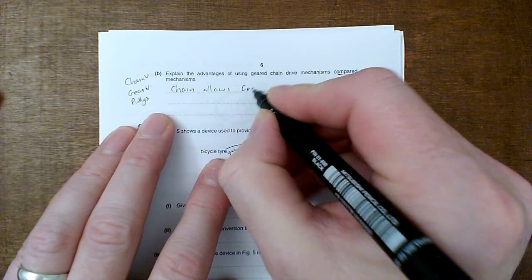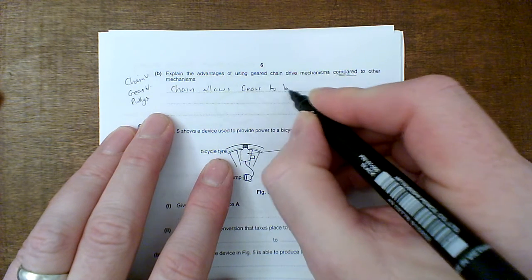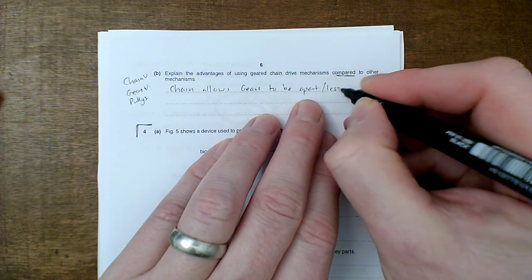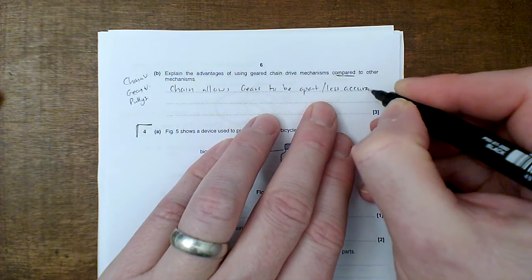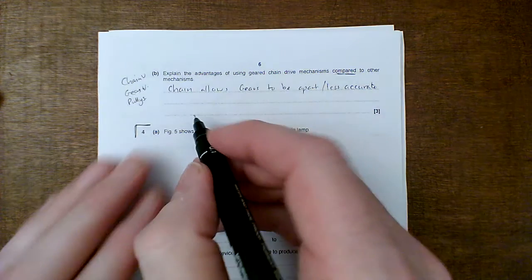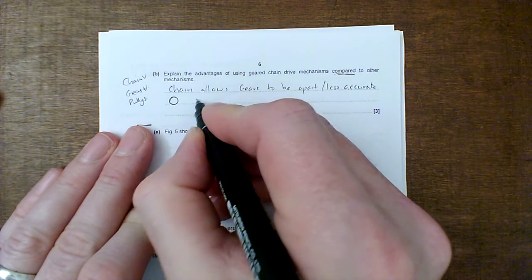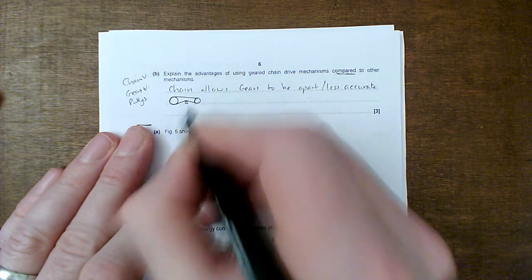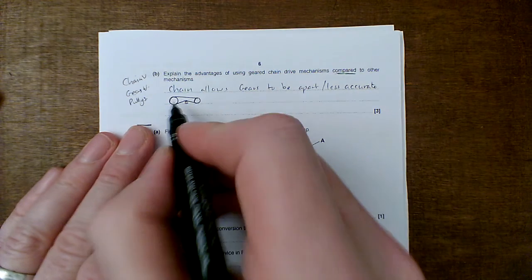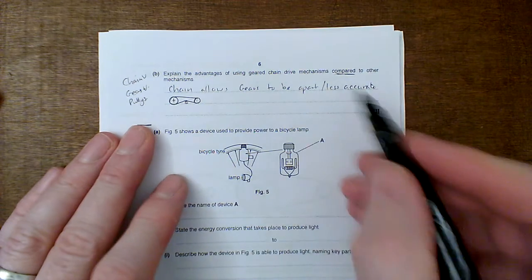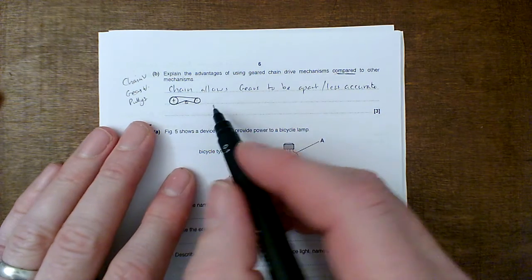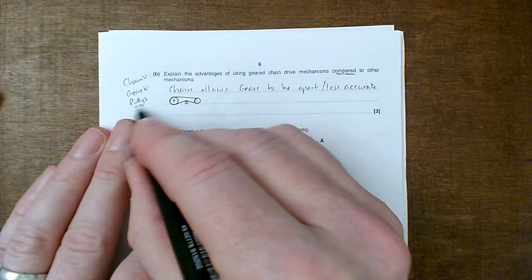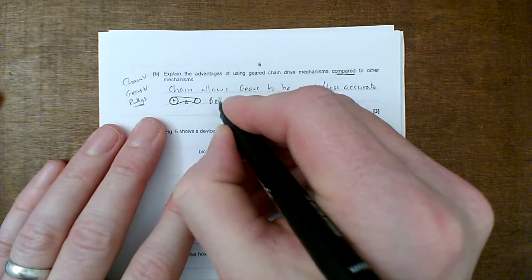The advantage of chain is it allows gears to be apart, so sort of less accurate. You think about your bike, it's got a system, so you can have a sort of a gear, another gear, and then you can sort of have a spring or something to sort of keep up the tension, so they don't actually have to be sort of super accurate. Okay,